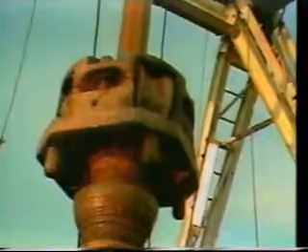When tripping into or out of the hole, the pipe is handled in stands, usually 2 or 3 joints each. First, the slips are set and the Kelly is disconnected, and the Kelly, rotary bushing, and swivel are stowed in the rat hole. With the Kelly unlatched from the hook, the elevators, which hang from the hook, can be latched around the pipe just below the tool joint. They can then be used to lift the pipe out of the hole.